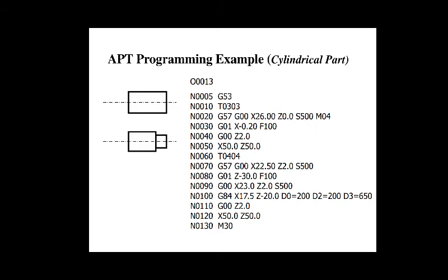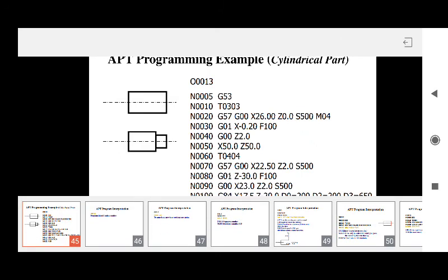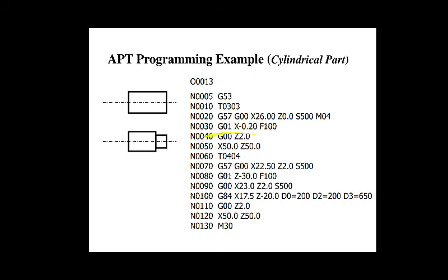with spindle speed 500 rpm. Now after that we are going to start the turning operation. Initially we cancelled the previous work 0 point, then we set the 0 point, then we performed the facing operation. After that, the tool moved away from the workpiece, then it went to the safe location, then the tool was changed. Then it comes close to the workpiece, and after that we are going to do the turning operation.